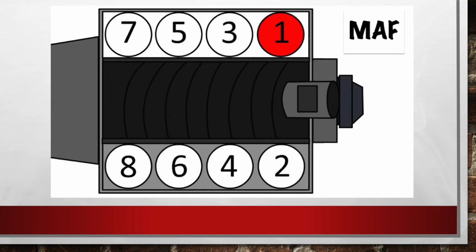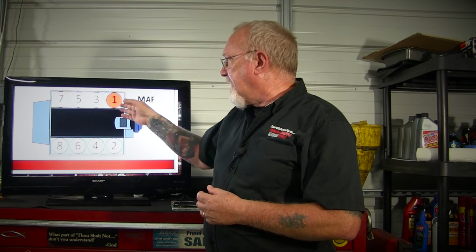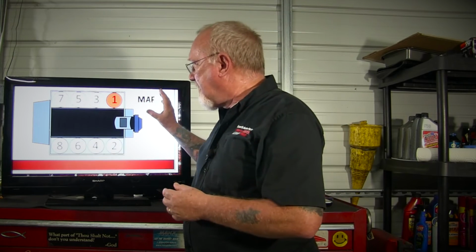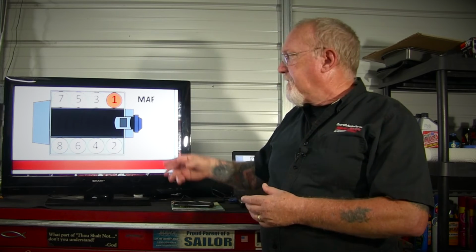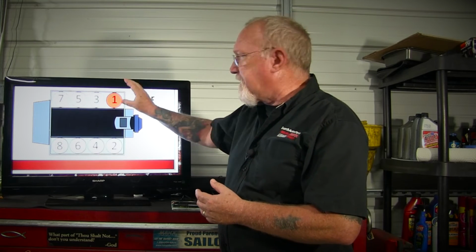So that total amount of fuel added to that 50 pounds of air into bank 1, each injector is going to get enough for 12.5 pounds of air. With me so far? And that's the bank 1 total that the ECM is going to send in. And then when that combustion goes past the upstream oxygen sensor, the ECM is going to report on how it did. With me? Bank 1, bank 2, total amount of air divided by 2, that's how much is getting into each bank. ECM makes this calculation, decides how long to pulse width the injectors to deliver the correct amount of fuel to each bank. And it gets its report when that combustion goes by the upstream O2 sensor.